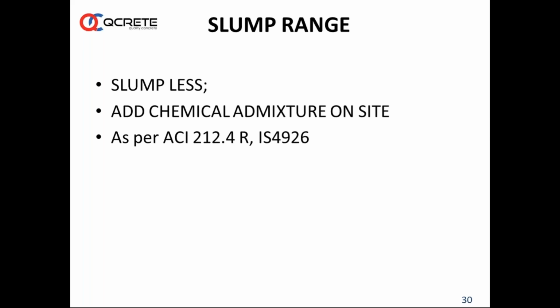I want to bring to your notice that we have other standards, the European standards, BS EN 12350, where a tolerance is given based on slump class, such as S4 and S3. For example, with S3 you can take the concrete between 80 to 170 mm, which means there is scope for the producer to deliver between 80 mm and 170 mm. Similarly, there is the S4 class, where a concrete producer can deliver concrete between 140 mm and 230 mm. So this is a more practical way of delivering the concrete.